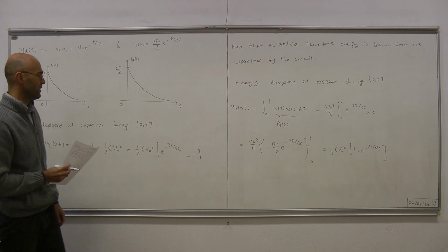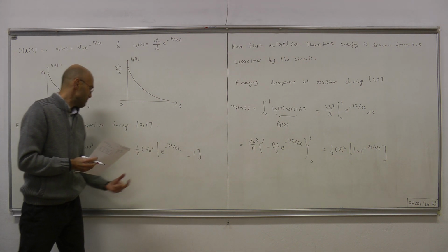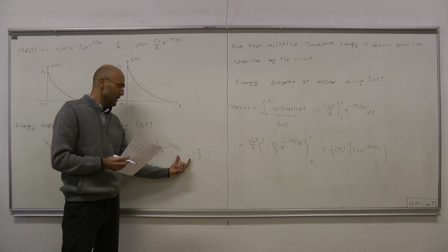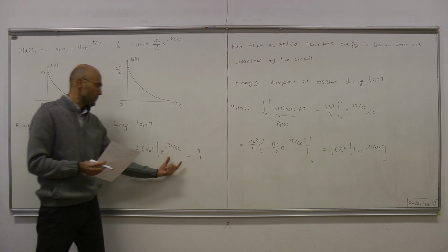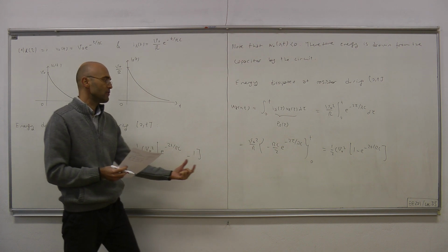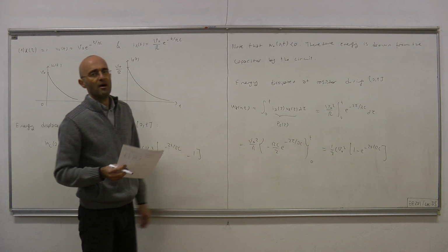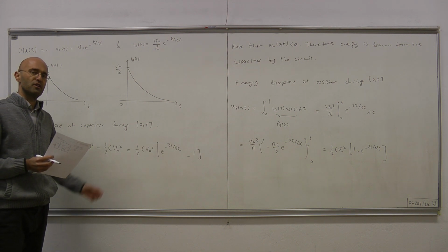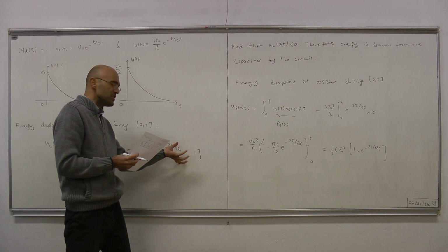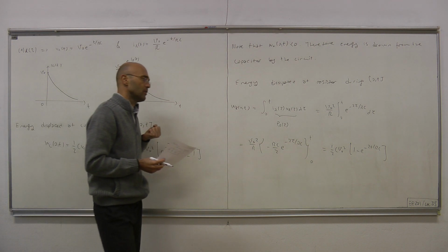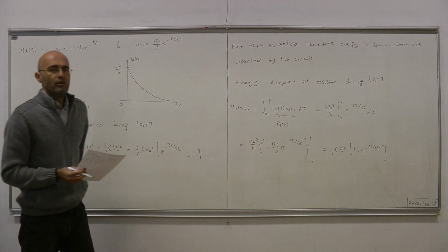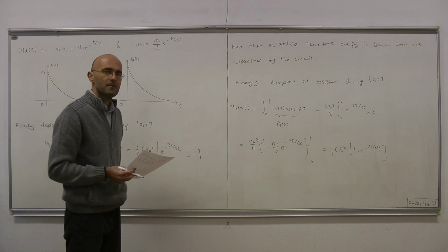Okay. Now that we have the same expression with a little difference, that the sign is opposite. Here we have something negative, and here we have something positive. The sum gives us 0, the sum is always 0, so that means energy is conserved in the sense that whatever energy is extracted from the capacitor is dissipated over the resistor, so everything checks out.